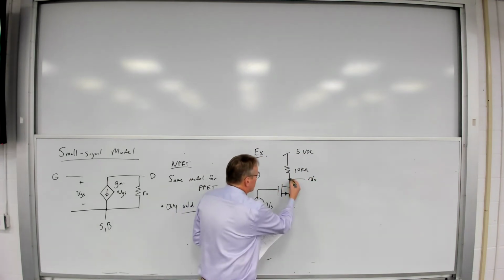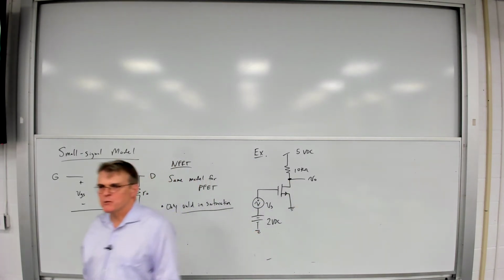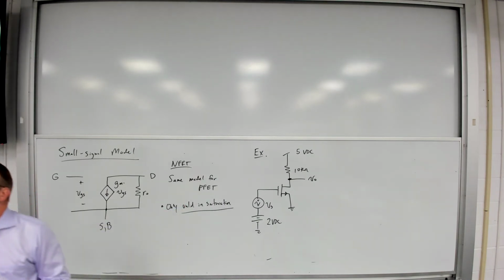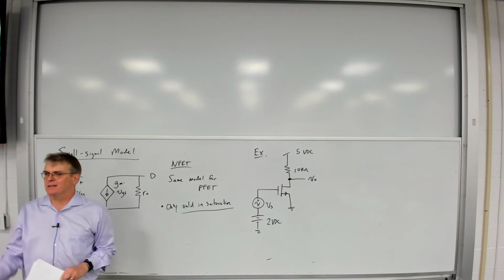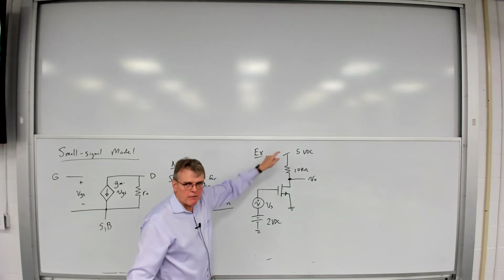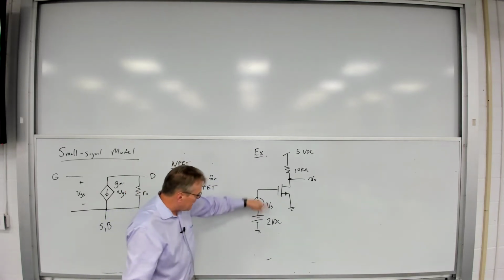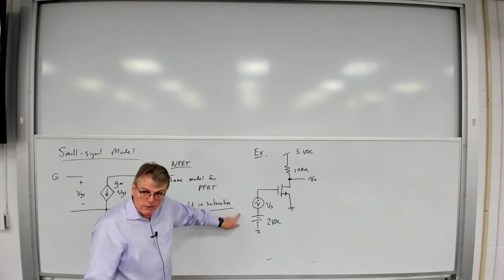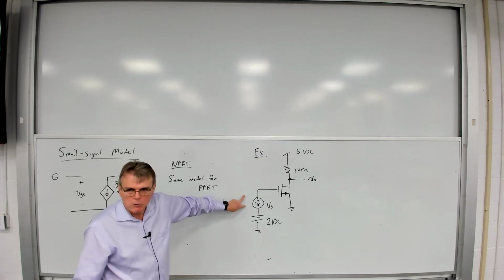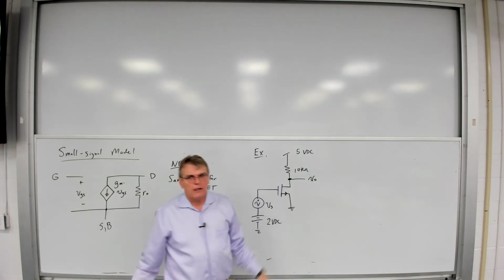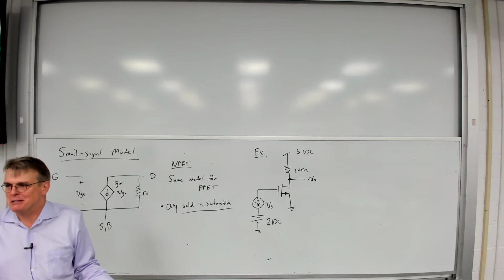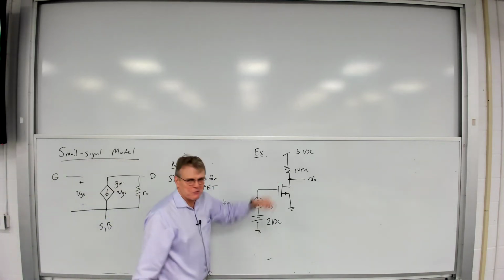Okay, here's our first amplifier circuit using a transistor. Now you're moving into real electronics. This is what people wanted transistors for when they first invented them, to do something like this. A MOSFET connected with a resistance between the drain and the power supply. I've got an input composed of a DC voltage, to set our bias point, plus an AC small signal input voltage V sub S. And I'm going to have a small signal output voltage at the drain, which is the only place that makes sense. There's no other node available that has any possible output but the drain of the transistor.